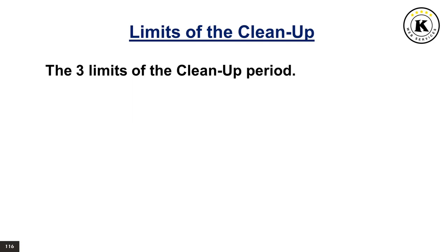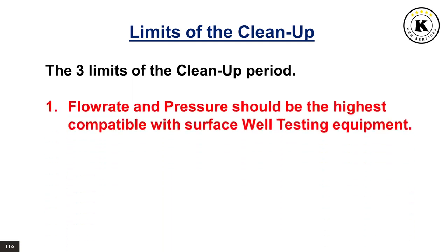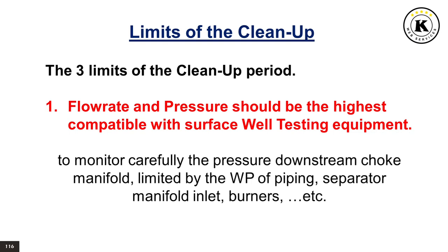Limits of the cleanup. The 3 limits of the cleanup period. 1. Flow rate and pressure should be the highest compatible with surface well testing equipment to monitor carefully the pressure, downstream choke manifold, limited by the working pressure of piping, separator manifold inlet, burners, etc.